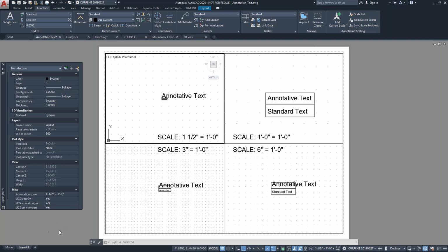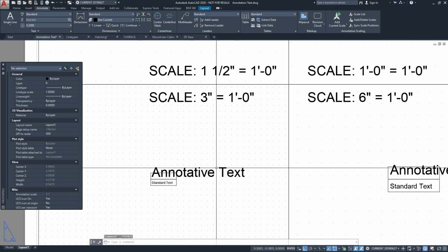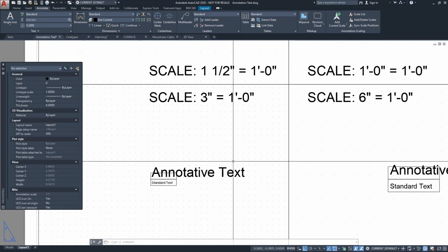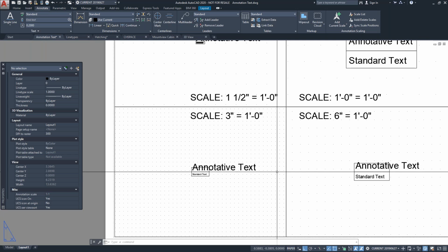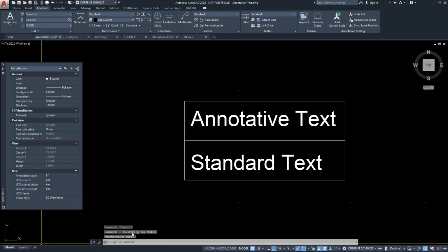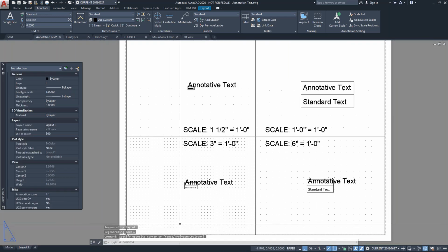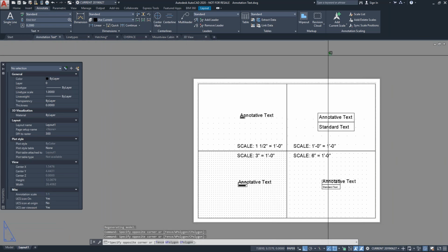Make sure that you review what the viewports look like before printing so that you know that everything looks accurate, especially because once you change the text size, it changes the size relative to the area of the model, and it may overlap the text on content that is not intended because you cannot see that in model space. So a lot of people work on content through a viewport so they can see where all the annotation is going to exist in the final printed product.